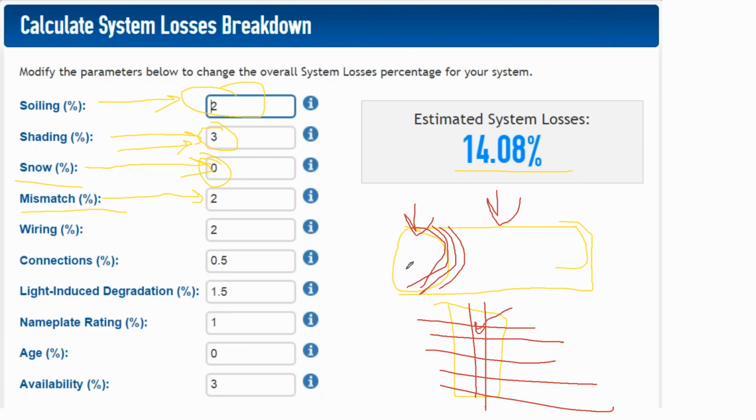And the reason why you have different wattages of different solar panels, this is rated for 270 watts, this is rated for 280 watts, and they come from the same manufacturer, is the manufacturer sorts these cells around before they test the panel and give it its rating in the factory. But even so, you're going to have as much variability between panels as within the product line. Here is a case where PV Watts is being a little too conservative, because it's saying there's a mismatch in modules, and the weaker solar panels are going to be dragging down the stronger solar panels.